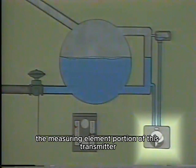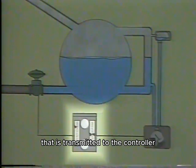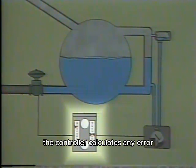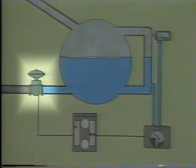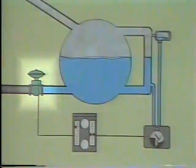The measuring element portion of this transmitter measures the differential pressure and converts it to a signal representing drum level that is transmitted to the controller, where it is compared to set point. The controller calculates any error and sends an appropriate control signal to the control valve. The control valve opens or closes to increase or decrease the flow of water to the boiler drum.